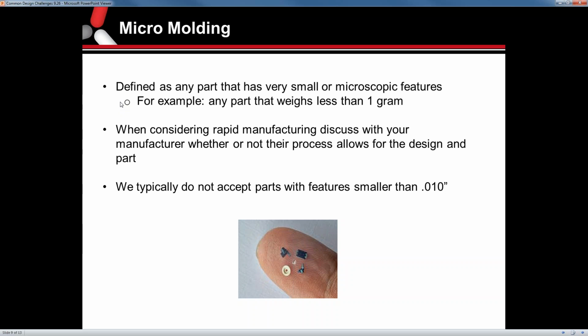It just doesn't fit within the rapid manufacturing process. It's a more niche type of mold. Typically any small feature that has a tight tolerance, like John said, any under 10 thousandths, is very difficult to machine without it being an expensive process, more EDM required. And then simply to fill that area out and have it be consistent. A lot of these features on some of these small parts could be deemed nothing more than flash, concentrated in a small spot.